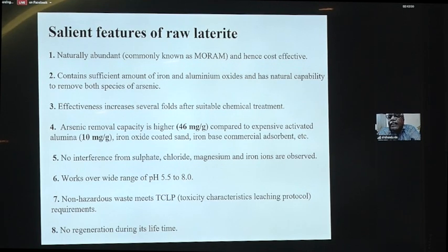So it's really a green solution. Since its capacity is very high and we are chemical engineers, we can design an adsorption column so that no regeneration is required during its lifetime. Its lifetime will be a minimum of 3 to 5 years. During its lifetime, the bed is not required to be regenerated. So it eases up the operational maintenance problem, and the recurring cost is very, very low.